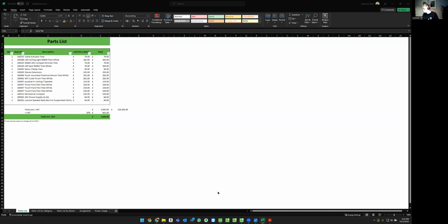And realistically, that central Miniserver, all it's going to be is just a Miniserver and maybe a relay extension, because the lighting in the thoroughfares just needs to be well lit. You could pop some presence sensors here and there depending on the size and how big the building is. So presence sensors, relays, extensions, and Miniserver just for the central control, which is, I can almost guarantee nine times out of 10, going to be cheaper than any other BMS solution out there, and it's all fully integrated with all the hotel rooms.